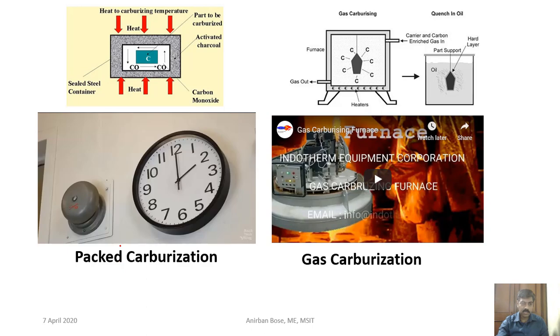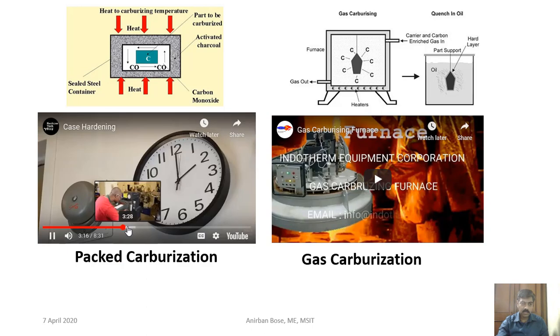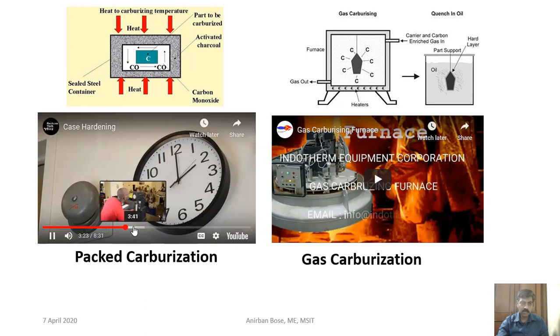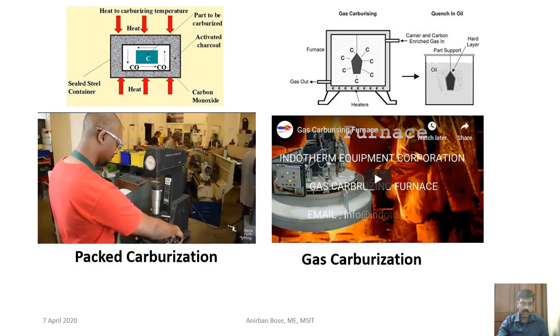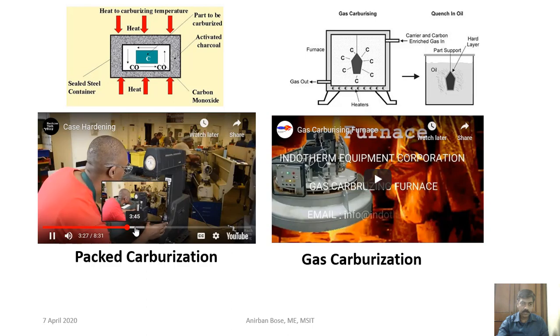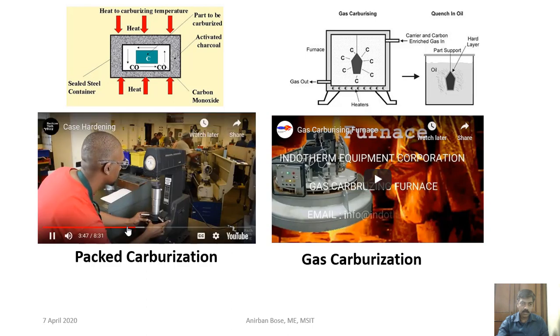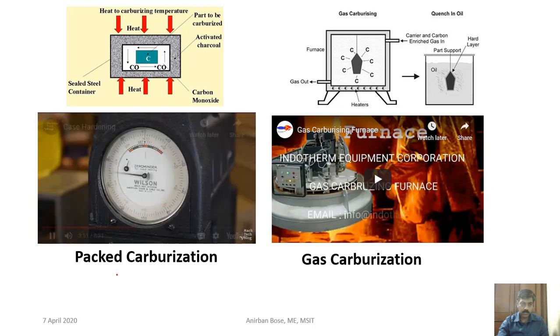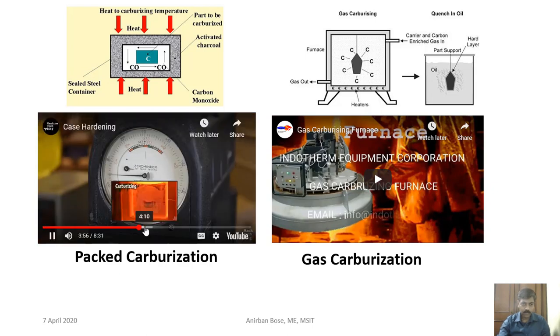You can see the temperature. We'll leave the box in the furnace to carburize for 8 hours. Since we've got some time to kill, let's measure the hardness of a piece of untreated 1018. The tip will penetrate deeper into the surface of softer materials than harder materials. A higher number on the Rockwell C scale indicates a harder material, with the scale topping out at 100.